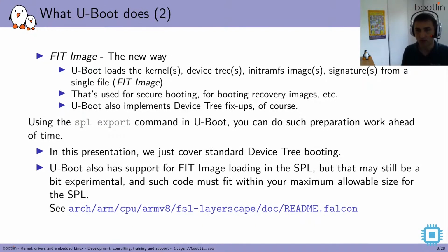So here we want to do all this boot preparation not in U-Boot, but in the U-Boot SPL. There's a command provided by U-Boot that can be used to prepare this work ahead of time. In this presentation, we actually just cover standard device tree booting, the FDT booting. U-Boot indeed has support for loading a FIT image in the SPL, but that's still a bit experimental in my impression. And another constraint is that this code must fit within your maximum allowable size for the SPL. You can read about it at this URL.